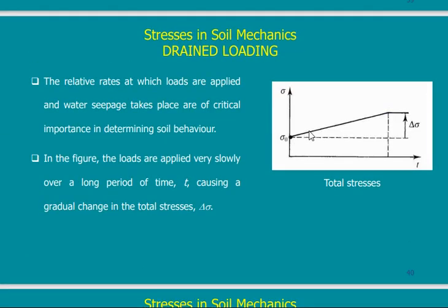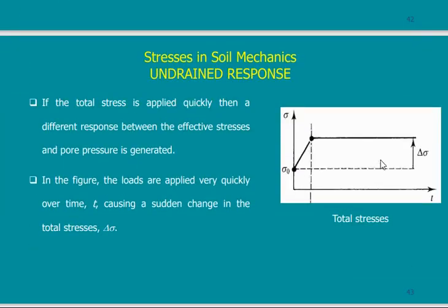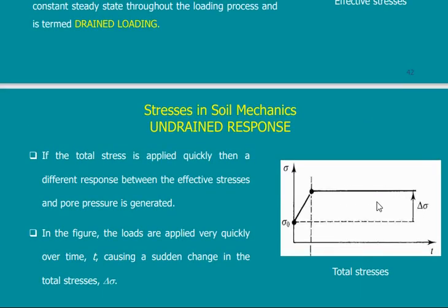I added the load till I reach the maximum load at the end of my test. But here you will find that you will start with the same point, but you will reach your maximum very quickly because water is carrying part of your load, and then it will stay like this. So this is the total stress.